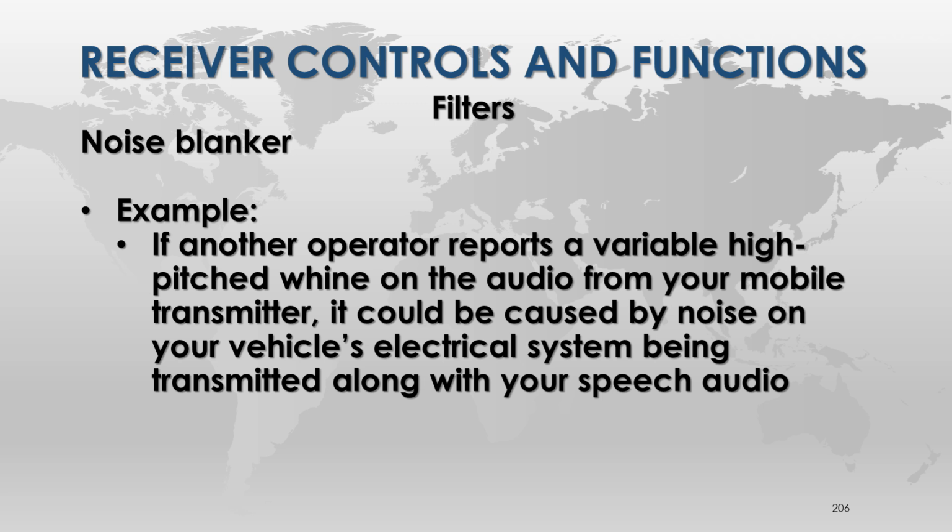Now, it used to do it with points and condensers. Yes. But does it do it with electronic ignition? Yes. If anything, it's worse. They've gone to some pretty great lengths to filter that out and keep it into that little computer module. But they've never made it go away. So in the old days, you might get 30,000 volts across the spark plug. Nowadays, it's way more than that. So that's going to make way more noise. But the filters have also gotten better, and they've had to filter them because they got computers in the car, and those noises would cause issues there. Yeah, they didn't do it to protect us, I promise you.